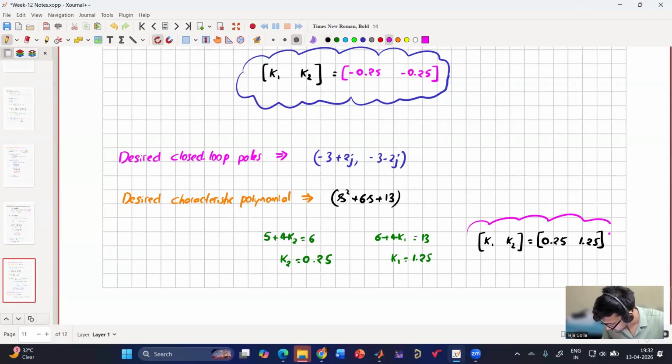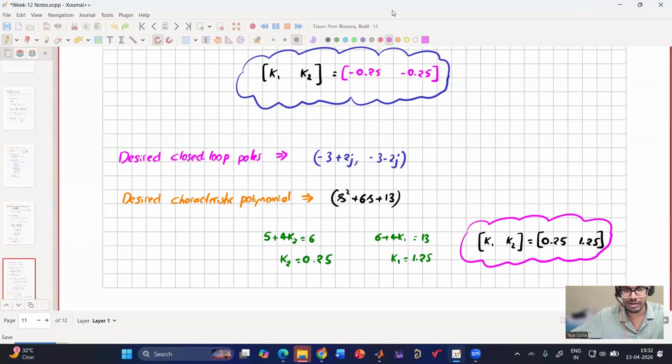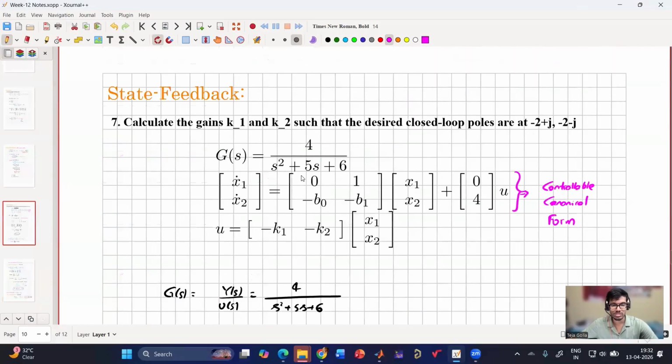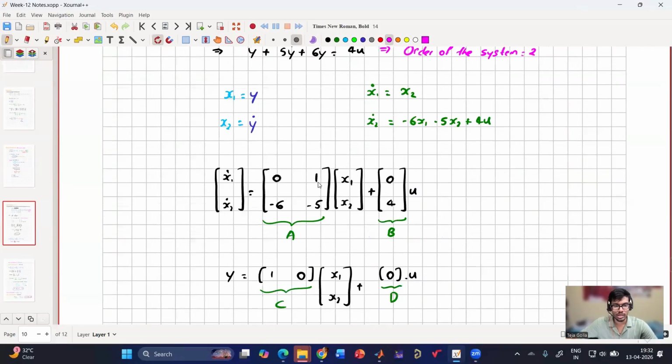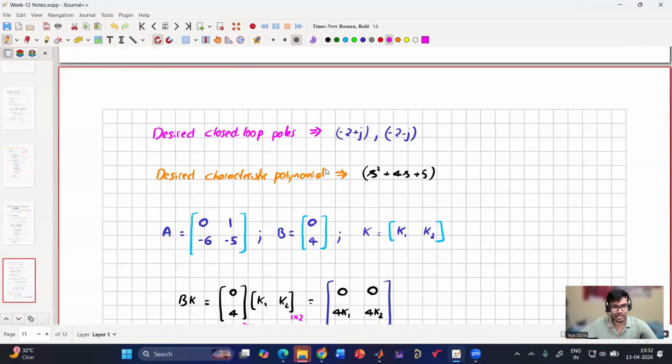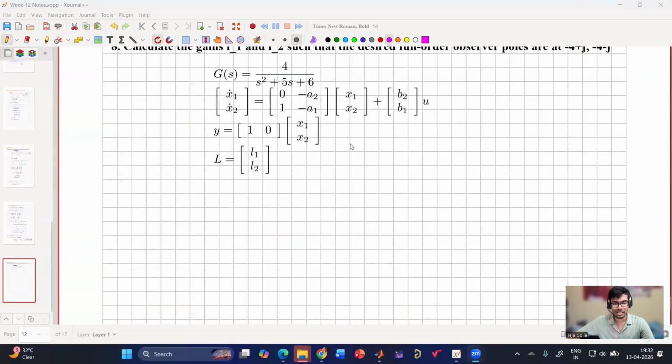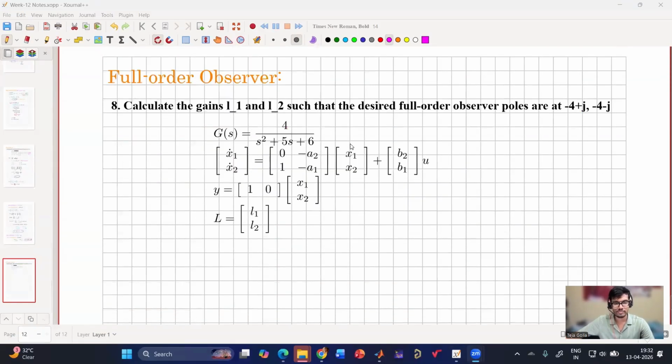So in this way, you can solve for K1 based on the desired pole equations. And we can also change some value in, say, the transfer function. Instead of 5, if I give 4, then this will become 4, and here this will become 4, and accordingly you can solve. So you can also see by varying what parameter, what is getting changed and how much. You can do all sorts of study based on this variable change or any parameter change. Is this clear until this point, Ravant? Any doubts you have?